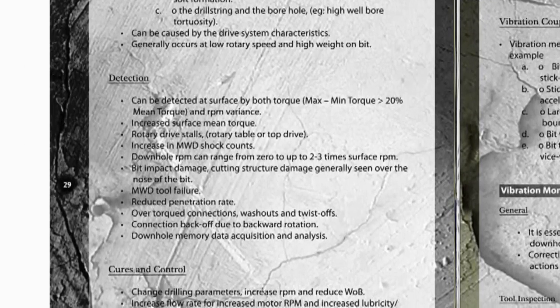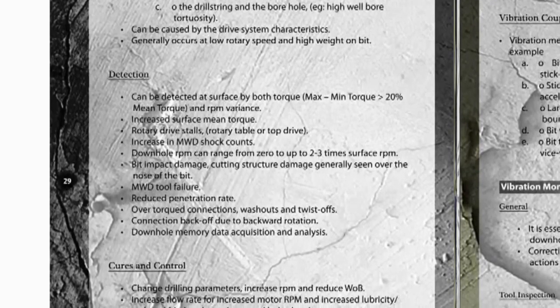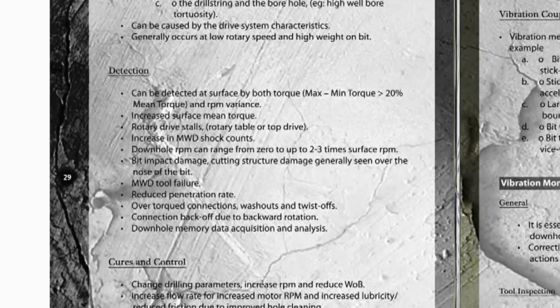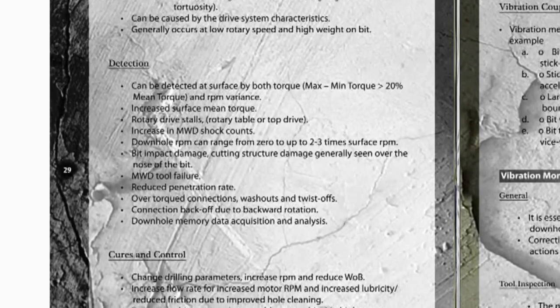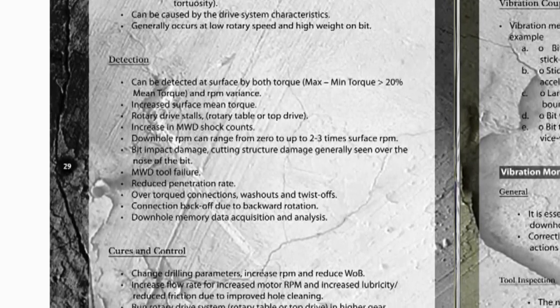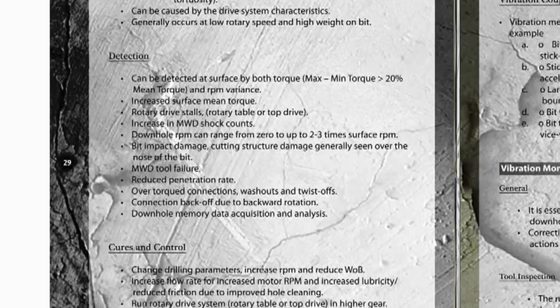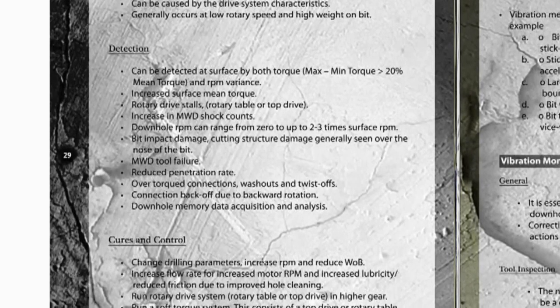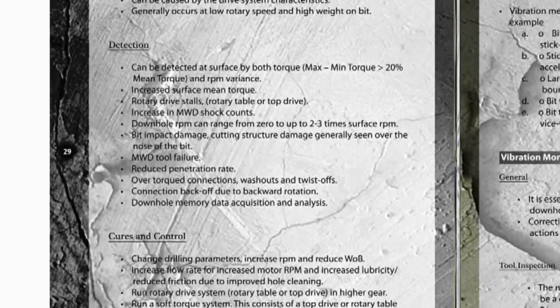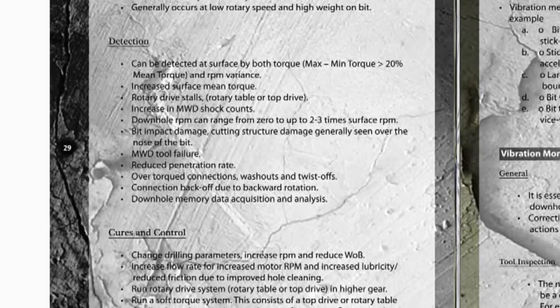Bit impact damage, cutting structure damage generally seen over the nose of the bit. MWD tool failure. Reduced penetration rate. Over-torqued connections, washouts and twist-offs. Connection back-off due to backward rotation. Downhole memory data acquisition and analysis.